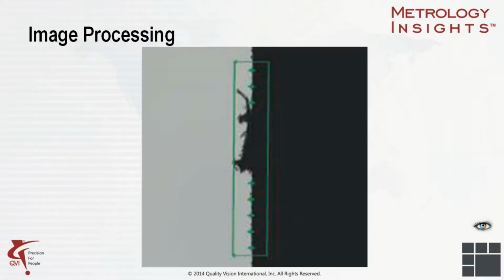The first sensor that we generally employ is vision. For a measuring machine to see, we have to give it eyes. That means using optics to image a part so we can examine it. Simple vision systems, such as microscopes, are good for visual inspections. A microscope allows us to magnify and see the detail more closely to spot a defect. In order to perform measurements, we have to go a step further and digitize the image so it can be analyzed by software. For that, we use a video camera.